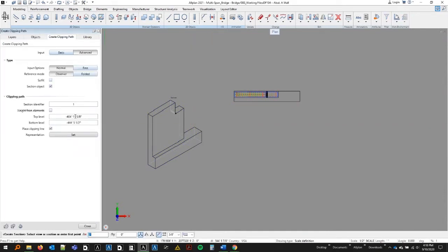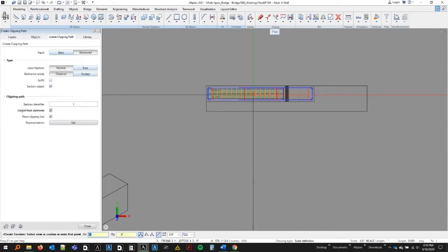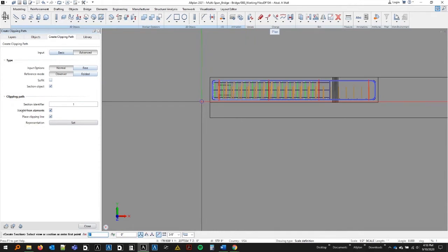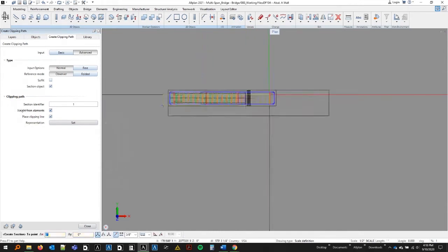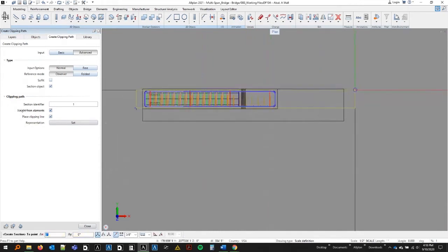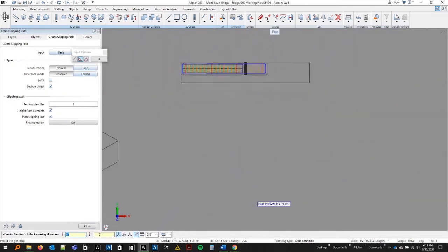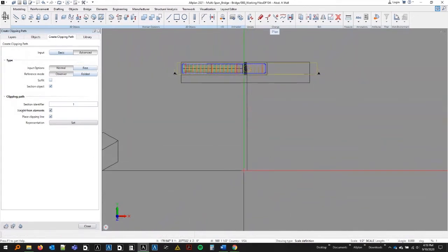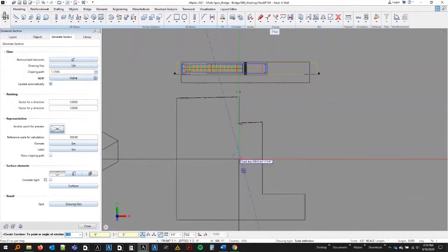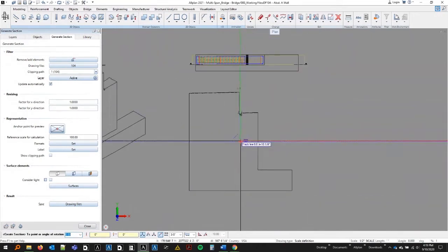The next thing we're going to look at is a section. So this is like a view, but I'm going to create a box or cube. Anything inside that cube is going to appear inside of my section. And now I choose a viewing direction. You can see I look at it from below, the left. These are the orthogonals, but I can split it. I can go to any exact angle I want. If I click inside this circle, it gives me a plan. And you'll see later on we can do even jagged cuts and more interesting things like that as well.